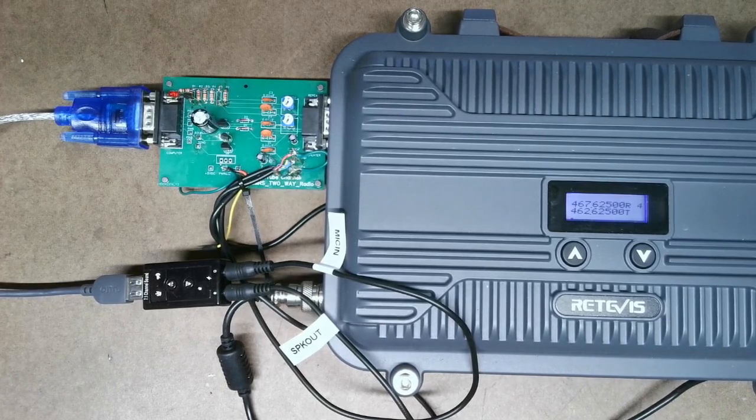Now like I said before, for my interface board, you need to get a USB DB9 adapter. When you get that adapter, you're going to have to install the drivers for it. Once you get the drivers installed, it should pop up telling you what your COM port number is. Okay? And if you don't know or you didn't pay attention, what you can do is go to,